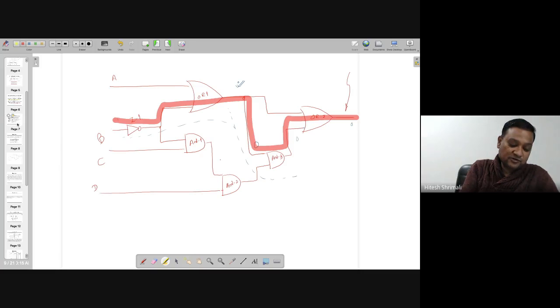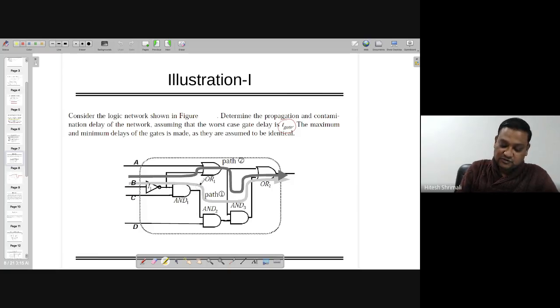However, another path was also drawn, which was taking 5 gates in a path, but the critical path is actually the one where the logic is changing and the output is depending. On the critical path, there are 4 gates coming, and that's why the propagation delay is 40 ps, as the delay from each gate is only 10.